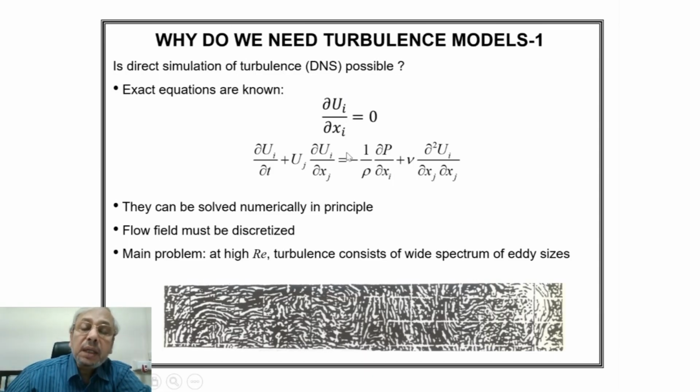simulation. But what one would need, number one, the discretization scheme should be absolutely error-free. Errors, like truncation error, diffusion error, artificial viscosity, dispersion error, all these errors should be tending to zero, almost zero. So these are special techniques, discretization techniques.